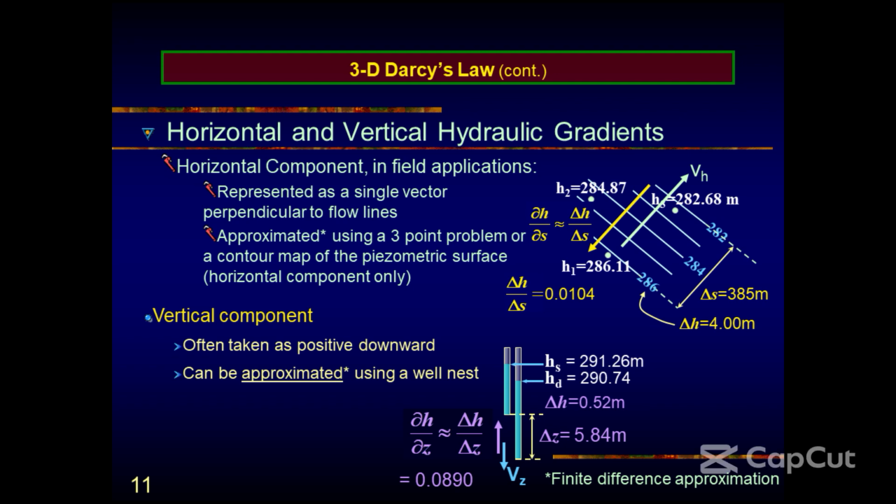You said the water in the capillary fringe is almost saturated. Yes. Why is the water not available to the aquifer? It's not available because it is held by capillary forces. It is tightly held to the aquifer grains, to the porous media, to the aquifer skeleton. Okay? All right.